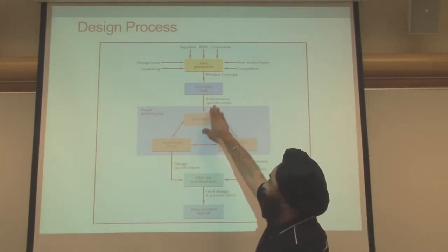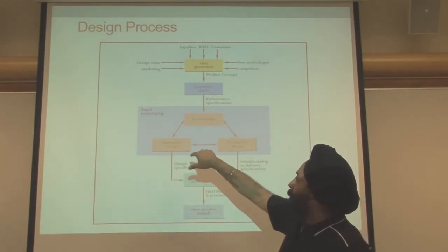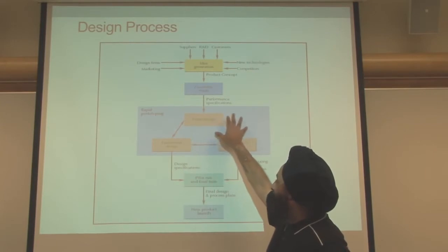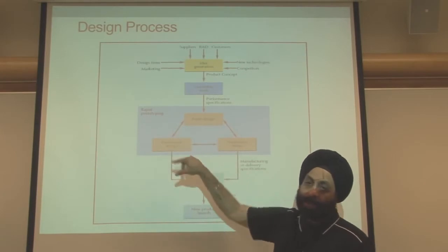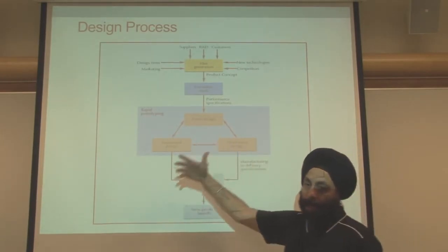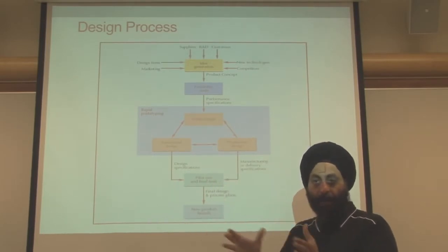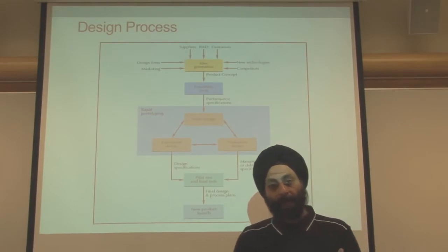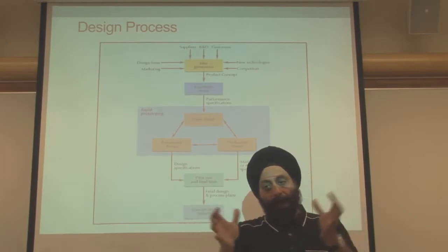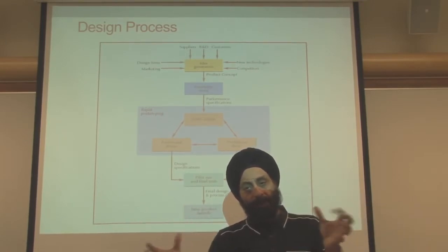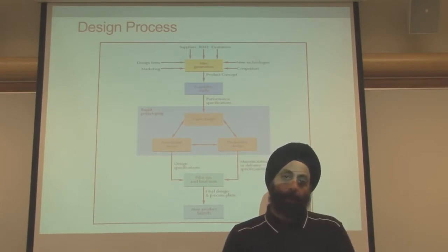From this feasibility study, once the performance specifications are out, comes the rapid prototyping, which is a way of taking the form design and, in rapid prototyping, you do these things synchronously, where you come up with the initial block design as to how the product form will look appearance-wise, and then the second part is the functional design, where the product may not look anything like the final shape, but it does exactly everything that the product is intended to do.